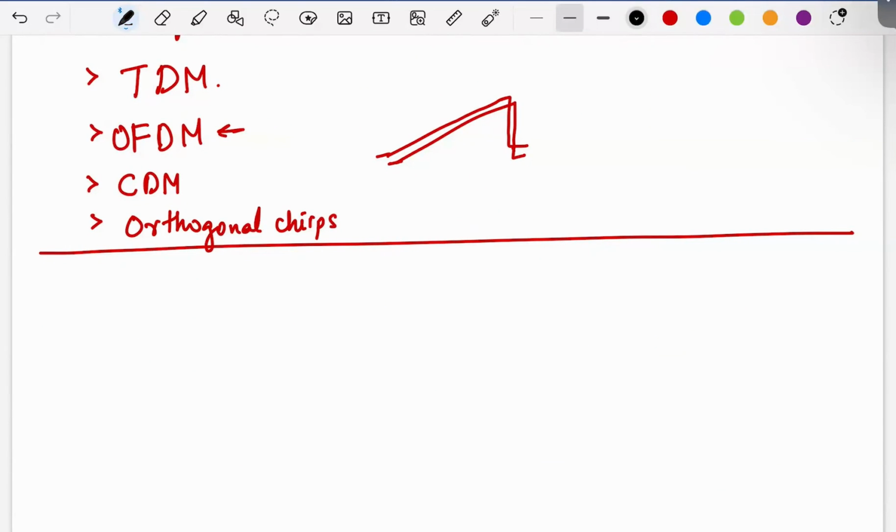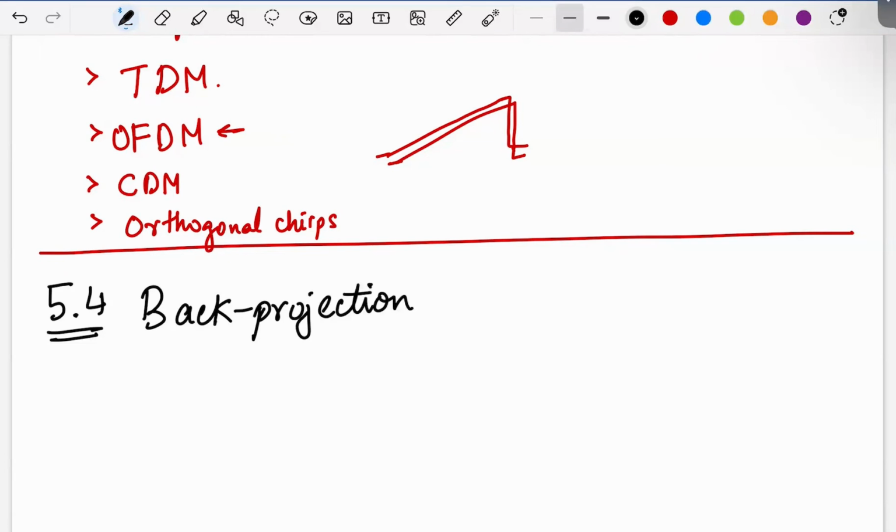Okay, so with that the conceptual part concludes. I'll end with back projection for image formation. So we saw, for example, for far field, if the target's in the far field, all you need to know is the phi component, phi nn, for different Tx and Rx. So if for the nth transmitter and nth receiver, you know what the geometric positions are in the far field, it's easy to steer the beam in that direction, right? You just compensate that phase and you add up the signals.